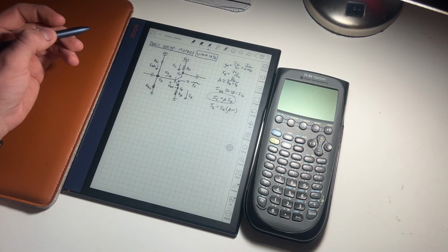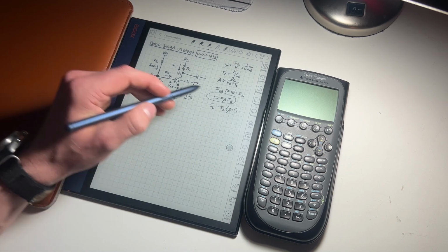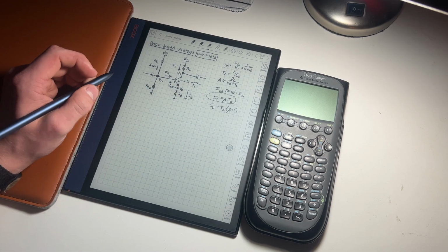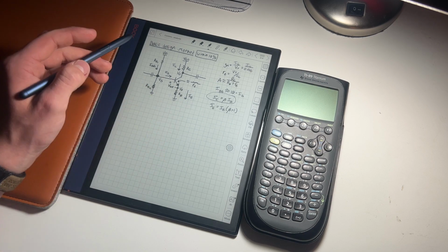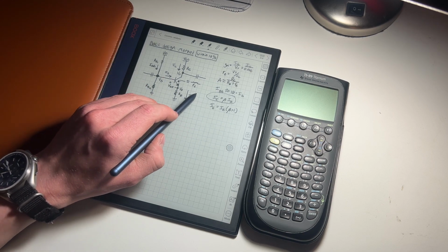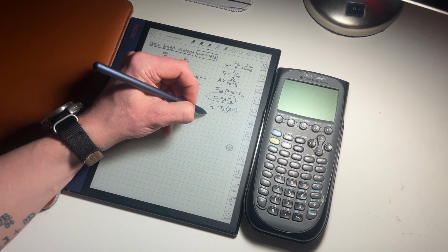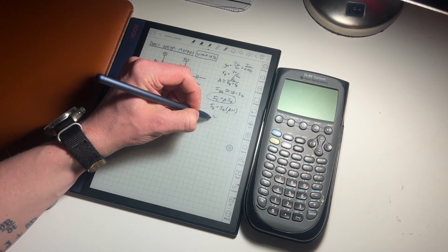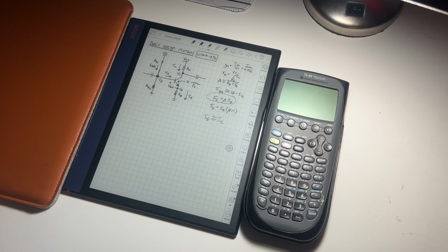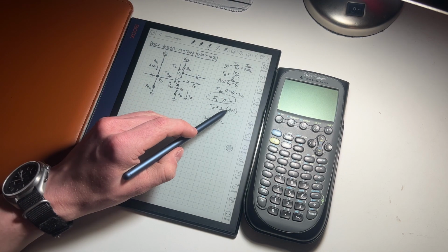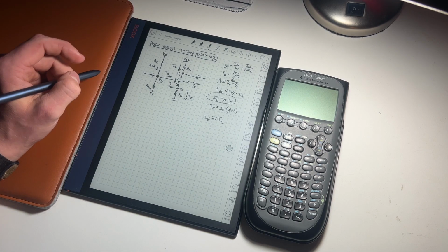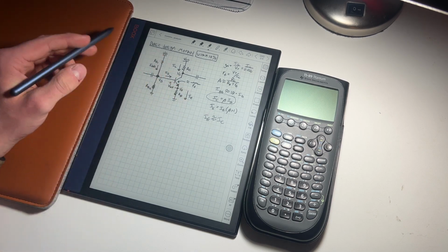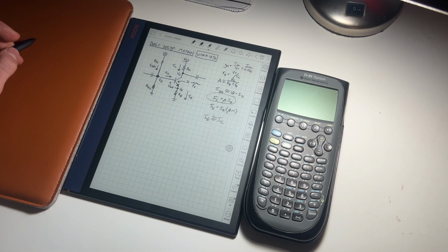However, like I said earlier, beta is typically pretty large, around 500. So later on, as I'll show you in the video, we make an approximation of IE being roughly equal to IC, because beta is so large that this plus 1 really does not add much to the whole circuitry. And this will just simplify things a lot for us when we start actually designing the amp.